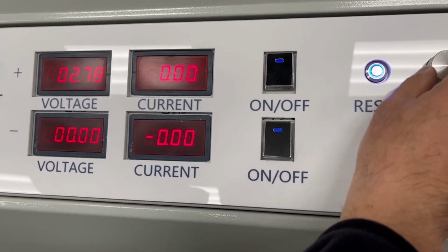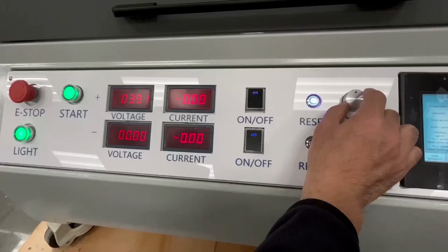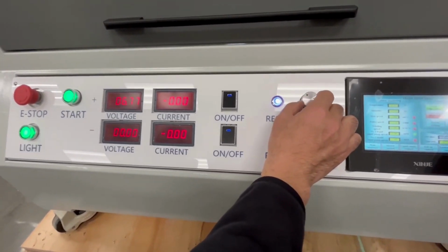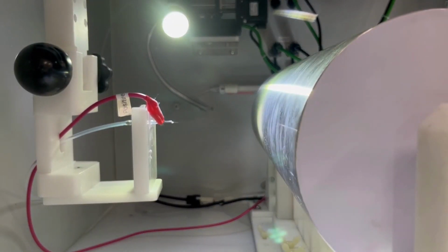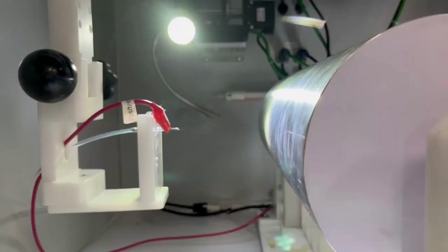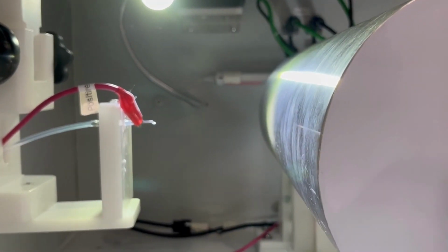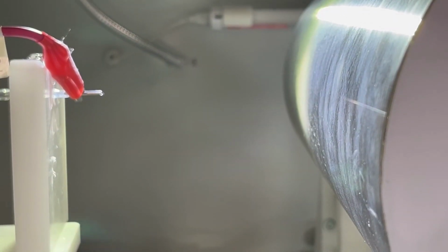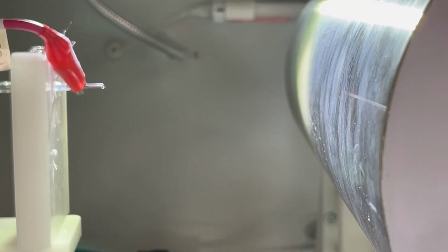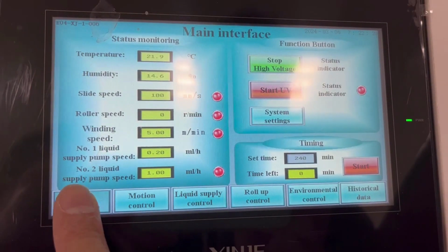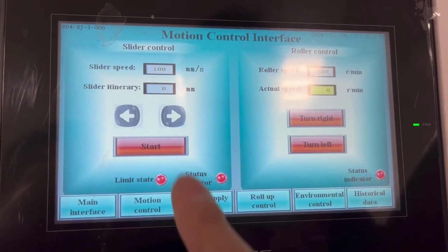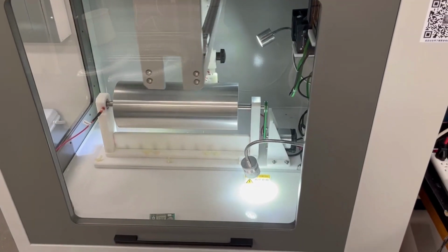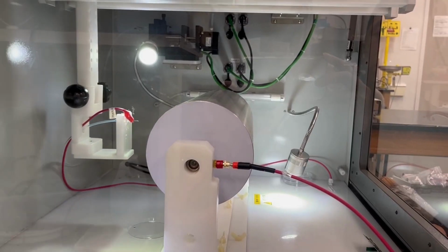The supply voltage setting to the needle is an important parameter to consider for nanofiber diameter and stable spinning. When high voltage is applied to the needle, a Taylor cone is formed at the edge of the needle due to the surface tension of the polymer solution and the electric field between the needle and the collector. In order to make a large area filter media and increase uniformity by collecting nanofibers along the collector, the needle can be moved left and right.